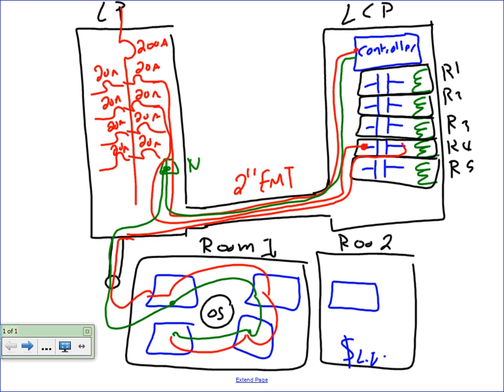Now, I haven't said anything about the control circuit yet. The control circuit, guys, I'm going to do the control circuit, and it's going to get a little bit interesting. So for the control circuit, I'm going to take a control circuit from here, a conduit, okay? This is for the control circuit, and I'm going to use blue this time. So the same relay, look what I'm going to have to do. I'm going to take this side of the relay, and imagine in a conduit. Are you guys with me? It's going all the way through a conduit, and I'm going to land this one to the occupancy sensor.